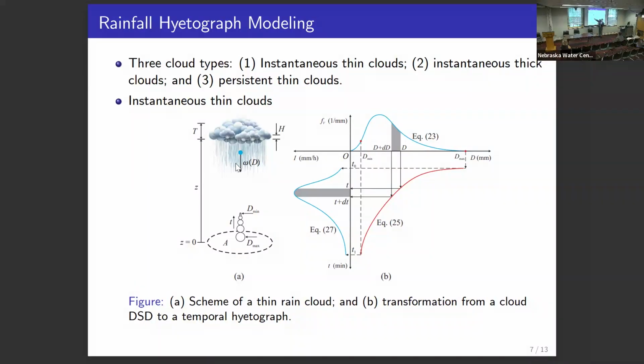So at this point, you know the rainfall stops. So this is the distribution. This is a small particle, this is a large particle, and this one we call the critical size. Particles less than this minimum will always stay in the air and do not produce rainfall. So the rainfall is produced by this part. This one first reaches the ground, so that is when rainfall starts. This point is the smallest one, and once this one comes, we say the rainfall stops.